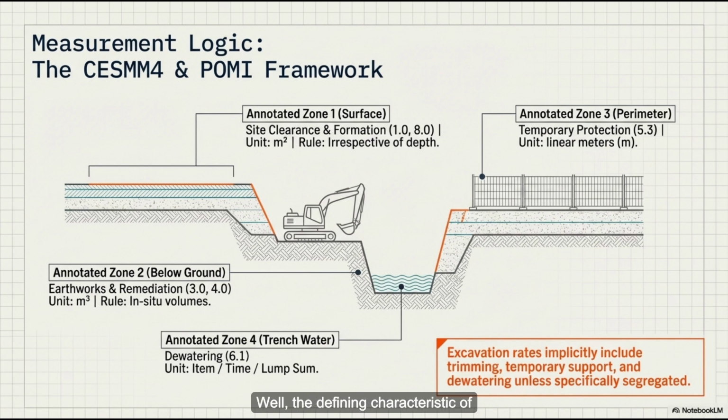Well, the defining characteristic of these rates is the explicit phrase they use. Fixed and not subject to any fluctuation. Not subject to any fluctuation. None. It locks the financial reality in place regardless of any macroeconomic shifts. So even if the economy tanks, exchange rates could collapse, local laws and regulations regarding source services could literally change overnight, and the unit rate remains untouched. Untouched. So the rate that the contractor quotes has to bake in absolutely everything. Labor, materials, transport, testing, overheads, and what the contract calls a sufficient contingency provision. You better have a good contingency.